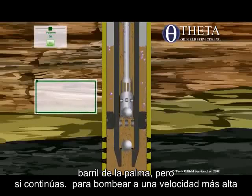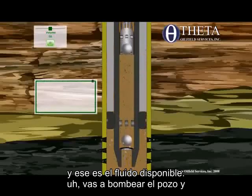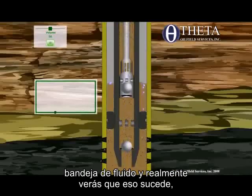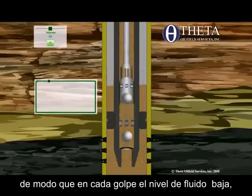But if you continue to pump at a higher rate than there is fluid available, you're going to pump the well off, and when you do that, you're going to have fluid pound, and you're going to actually see that happen. So every stroke, the fluid level goes down.